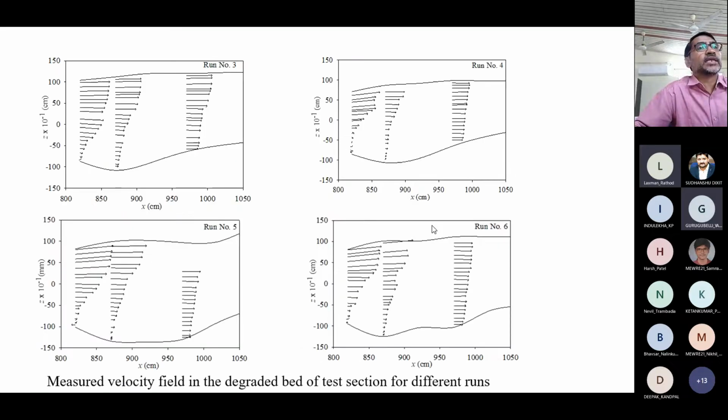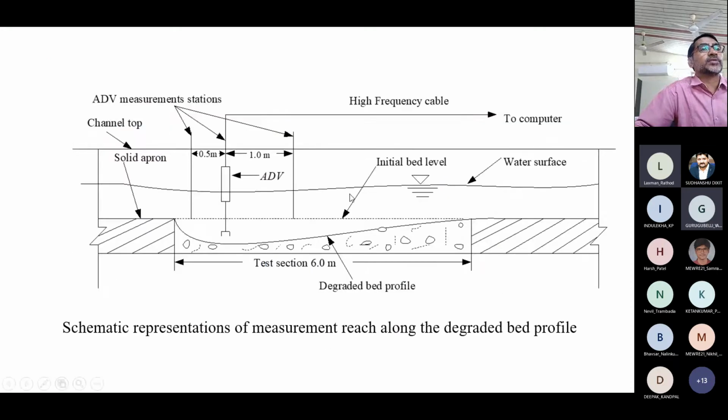If I go back to this section drawing again, see this one. Maximum turbulence is here at section 1 in terms of turbulence intensity. Some turbulence is there at section 2, and as water reaches up to section 3, more or less the whole turbulence has settled. So we are getting a lesser amount, meaning variation is not there. Whatever range is there, there is not much variation as you go across the depth. It is all right, Neerav?